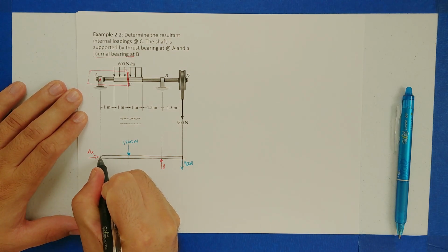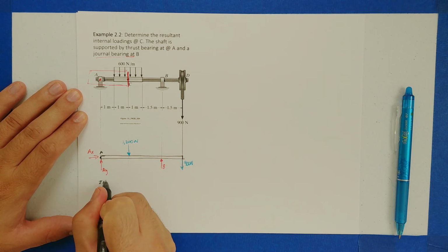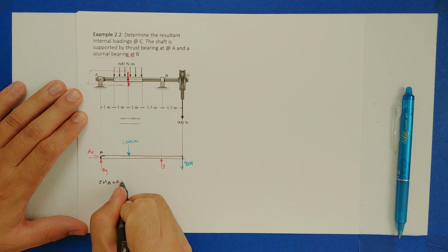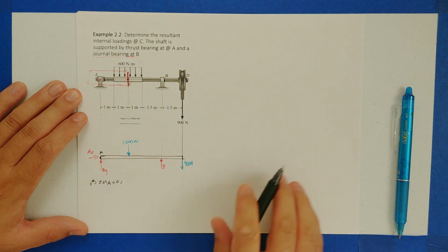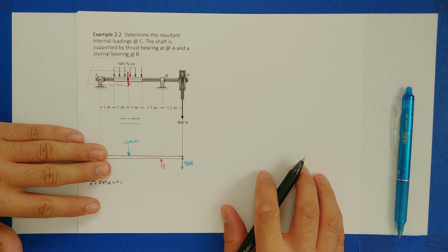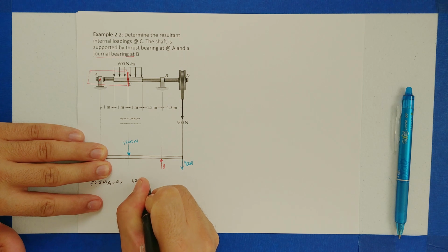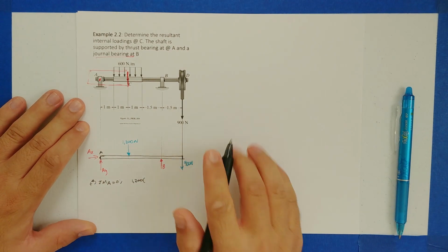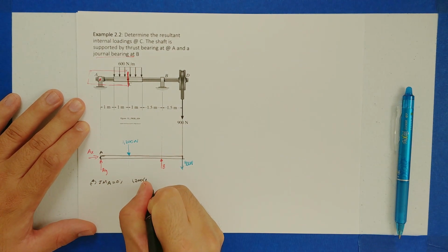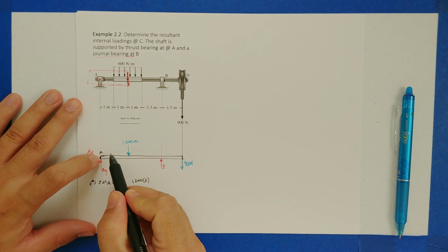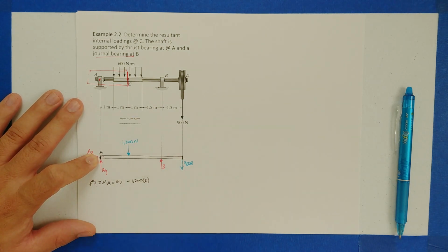I'm going to sum the moments at this point A so we can solve for B. So summing the moments at point A, making them equal to 0. Remember our convention, counterclockwise is positive, right? None of these are going to cause a moment. The 1200 Newton force will, so 1200 times a distance from point A to the centroid of 2 meters. If we're pinned here, this force is going to cause a clockwise or a negative moment.